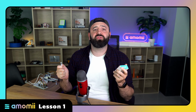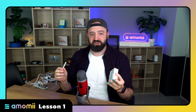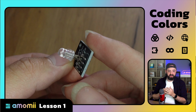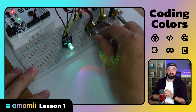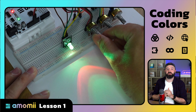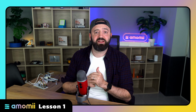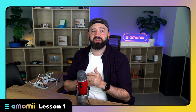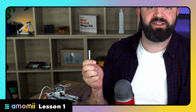To get an understanding of what addressable RGB strips are, we'll look at a regular RGB LED and talk about some of the issues. A regular RGB LED is basically three LEDs built as one, either with their cathodes or anodes connected together. You simply control the amount of power going through each color to create other colors. I have one here set up to demonstrate. Theoretically, as I turn these dials controlling how much power goes through the red, green, and blue filament, I can create any color. This works fine, but I need 3 signal lines for just one RGB LED. Now, if I wanted to control 1,000 LEDs, I would need 3,000 signal lines. This is obviously unrealistic. That's where addressable LEDs come in.